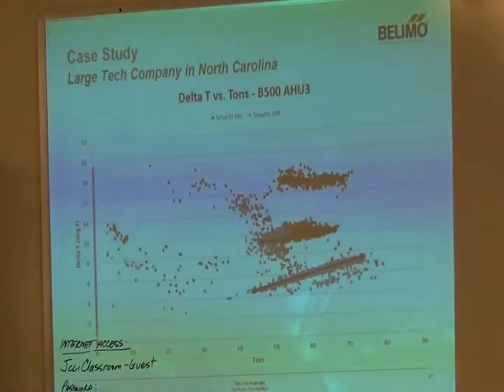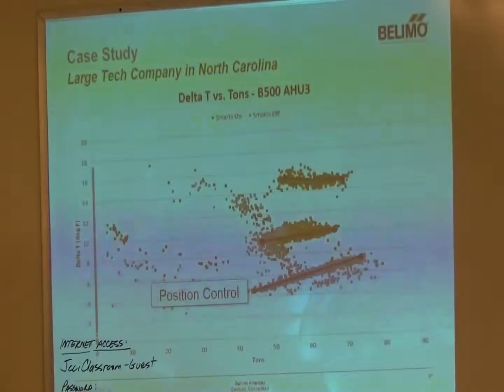This is another case study that we've done. We don't have it printed up yet. We're still working out details with the company as to whether they want to be involved in a case study. But they are allowing us to show this. And what this is going to show, Brian was talking earlier about being able to set up the valve as a pressure-dependent valve as well. So what we're going to look at here is this line down here. That's showing the valve set up in pressure-dependent mode. So that would be just like if you had a standard two-way characterized ball valve, a globe valve in the system.